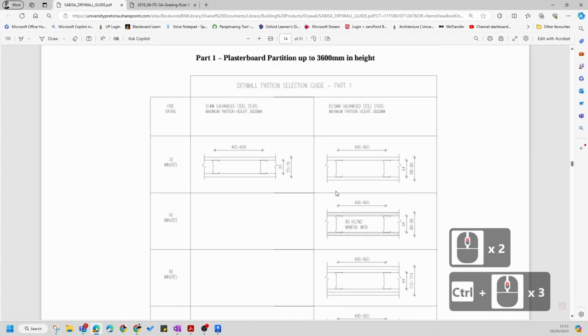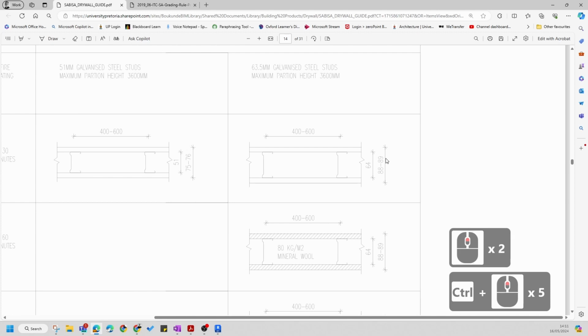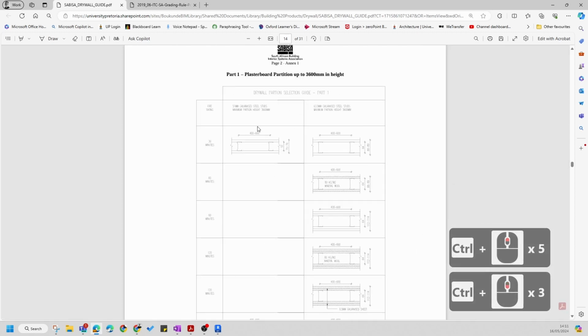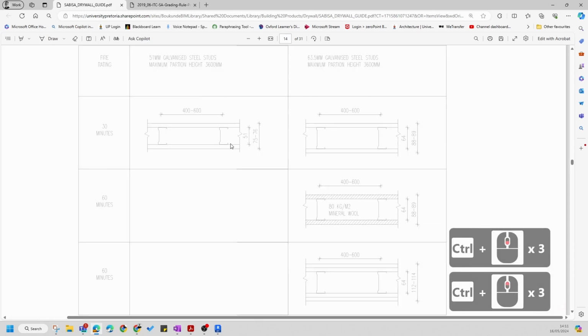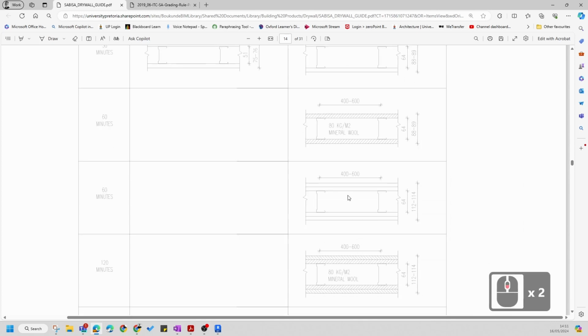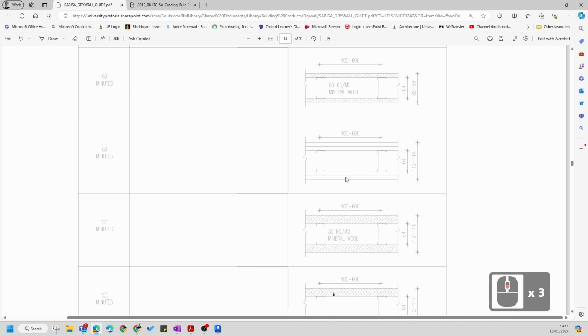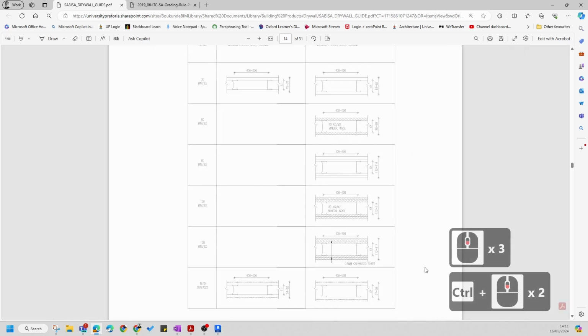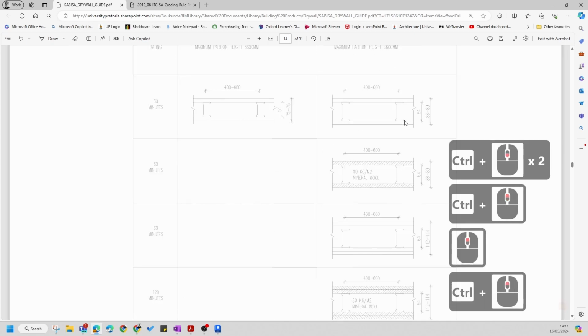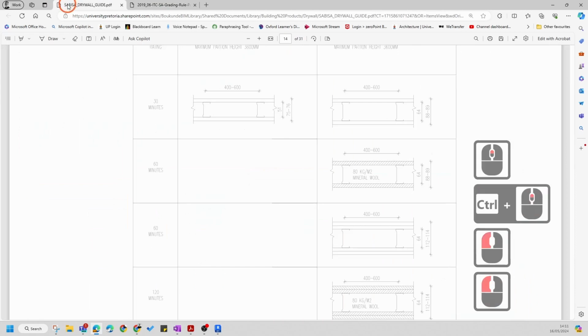Okay, the different thicknesses. You get an 88 to 89, you get a 75 to 76. Here they give you all the specifications, and this is a 30-minute fire rating because it's got a board interior and exterior. If they put a double board, like I was saying, then it becomes a much more fire-resistant wall. You can see these combinations just give you more flexibility, but I'm going to make this an 89 stud wall. So this is very easy to do now.